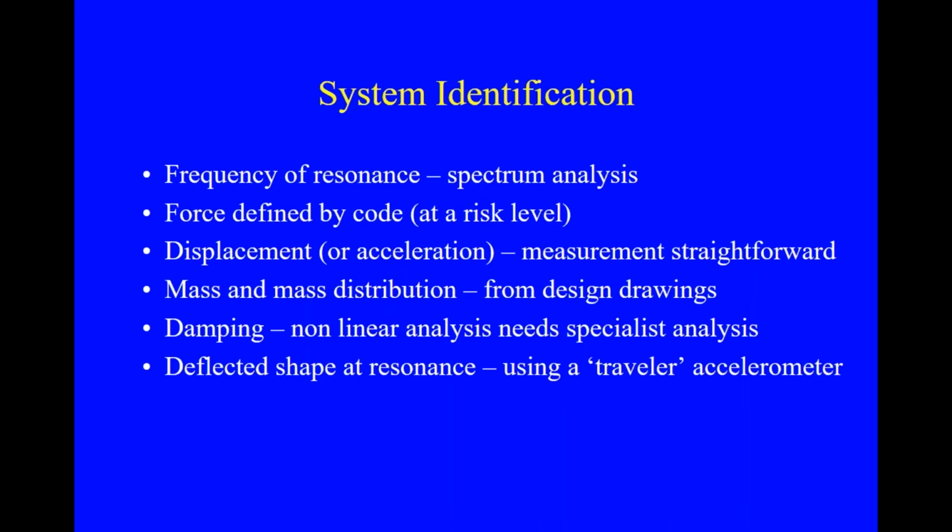And then we guess at damping. We guess. We put a value in that everybody thinks is okay. Well, let me tell you, it's not okay, and there are many errors associated with the values that people are taking. Now that, in AS/NZS 1170.5, leads you into these graphs where you make a choice of damping at 5%, 2%, whatever. But it's a nonlinear parameter.